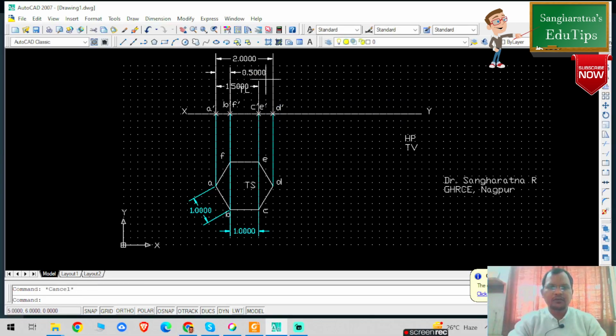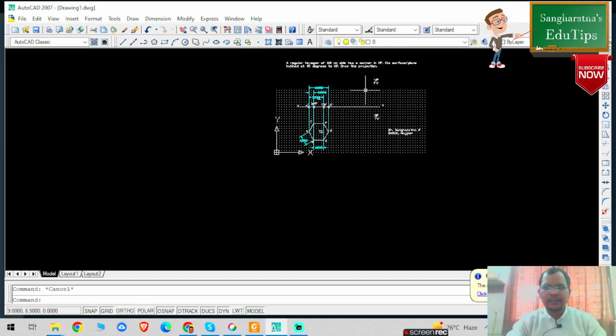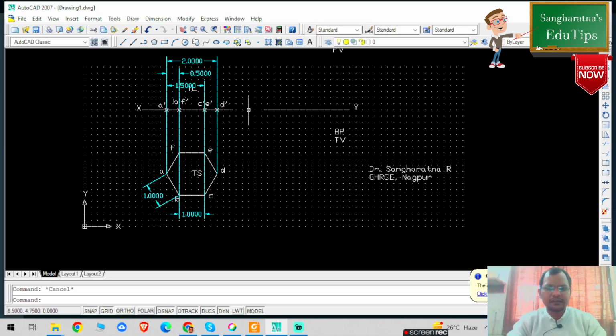Okay, and now I am converting this particular dimension into cyan color. Now press escape. So my true length, true shape, everything, top view and true length inclination will be in white color, and the rest of the things will be in cyan color. Okay, now it is given in the problem statement that I have to incline its surface of plane 45 degrees to HP. That means this true length will be inclined at 45 degrees to HP.